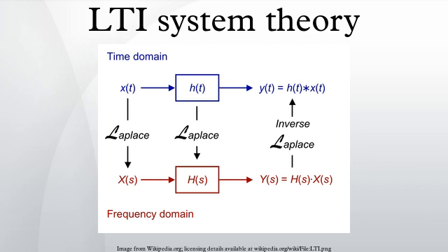Causality. A system is causal if the output depends only on present and past, but not future inputs. A necessary and sufficient condition for causality is: where h is the impulse response. It is not possible in general to determine causality from the Laplace transform, because the inverse transform is not unique. When a region of convergence is specified, then causality can be determined.